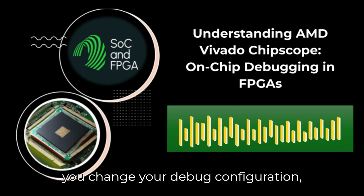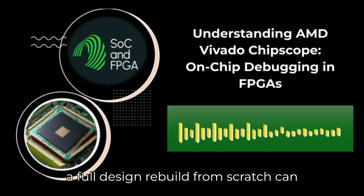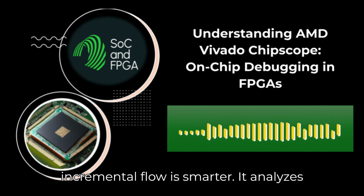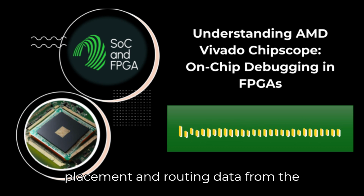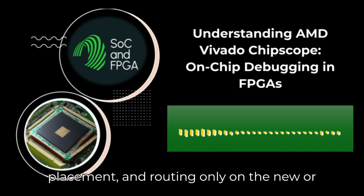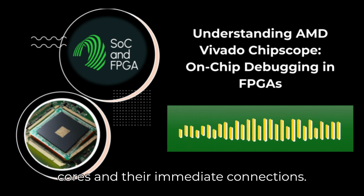When you change your debug configuration, maybe add a new ILA or change its depth, a full design rebuild from scratch can take hours. Yeah, painful. The incremental flow is smarter. It analyzes what changed and intelligently reuses placement and routing data from the previous run. It performs synthesis, placement, and routing only on the new or modified logic, basically. Just the debug cores and their immediate connections.